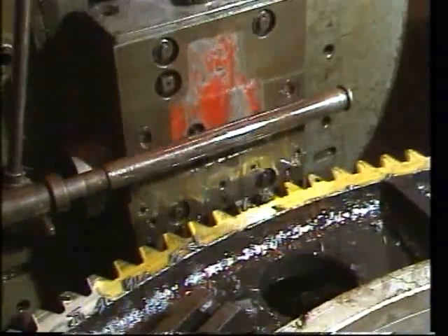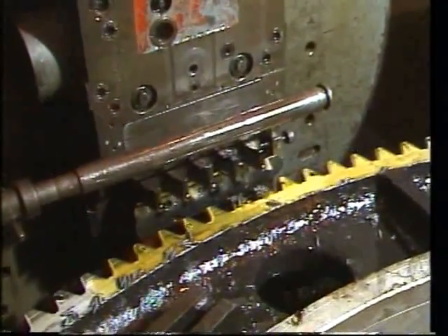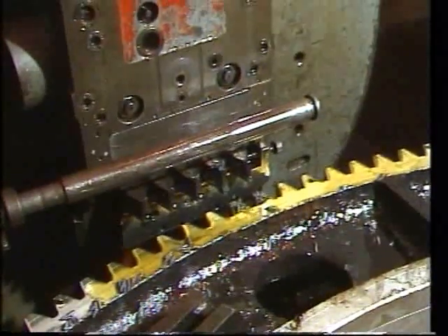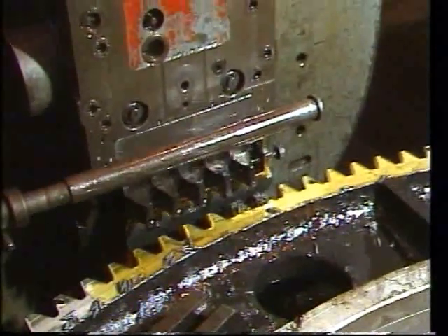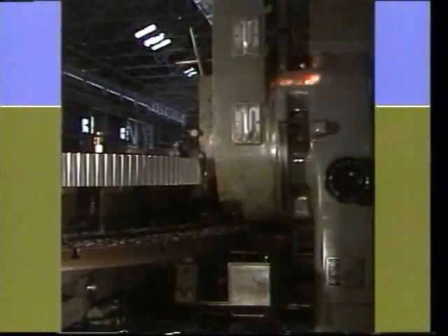As the blank and tool move along the respective paths, the cutter removes a small amount of metal each time, causing a series of facets that produces the involute curve form. This method results in production of teeth accurate to any size using only one cutter for a given module.